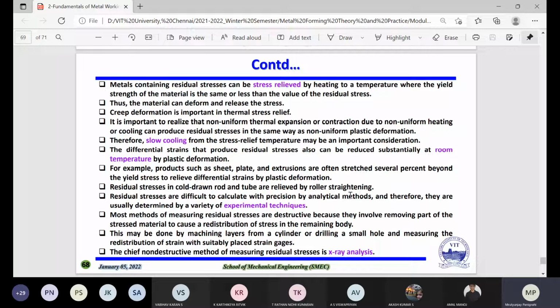And one more thing, which you will get to know when you do some research: whenever you are using any kind of heat treatment in a furnace, there is a thermocouple inside, and that thermocouple is showing the furnace temperature. But whenever you put the sample somewhere in between the furnace chamber, the temperature there is different, because the furnace thermocouple is somewhere far from the sample area. Maybe 30 millimeter, or 40 millimeter, or 60 millimeter.